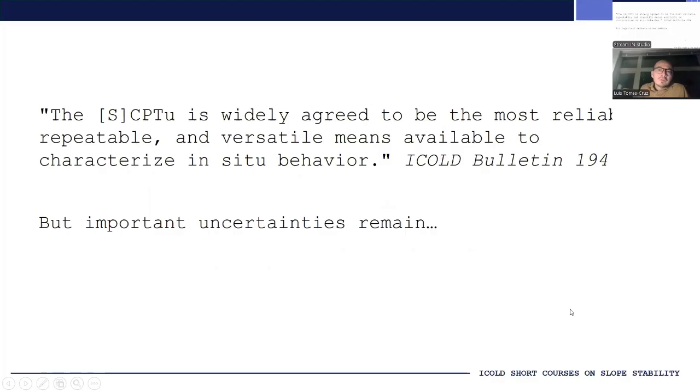Moving on to in situ testing. Just want to check how I'm doing with time. Okay. Moving on to in situ testing, the bulletin points out that the CPT is widely agreed to be the most reliable, repeatable, and versatile means available to characterize in situ behavior.